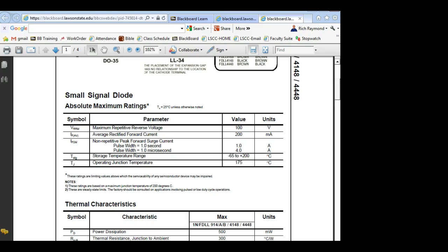First of all, in a data sheet for solid state devices, they give you the temperature that all the measurements were made in, because we know that solid state changes with temperature, right? 25 degrees centigrade, which is right around 73 degrees Fahrenheit, they figure to be what we call ambient temperature. So just about all your solid state devices are going to be rated at 25 degrees centigrade.